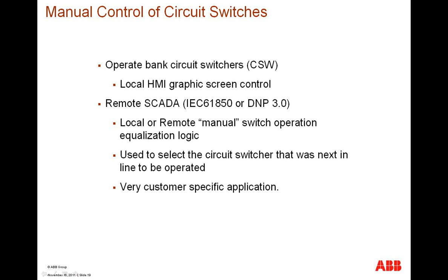The manual control of these circuit switchers has to be done by either the local graphic screen or remote HMI screen. They must have the remote SCADA and local or remote manual switch operation in the equalization logic. The equalization logic is going to help us assure that the same circuit switcher associated to a particular capacitor bank is not used multiple times, while the rest of the circuit switchers associated to other capacitor banks are not used near as much.